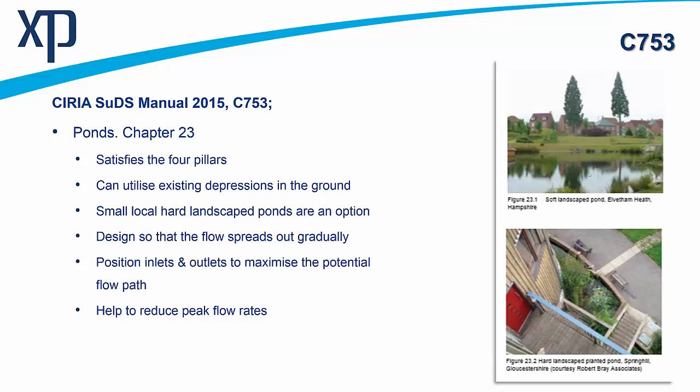We're not utilizing the full benefit of retaining that water for at least a 24-hour period to get the silts and the pollutants to drop out and give that final polish, that final clean to the runoff before it discharges off-site. We'd like to put in a long, tortuous path to make sure that that happens. There are some good examples of putting underwater bunds, actually, to create continuous paths below the surface that are quite neat to be aware of. And the ponds themselves will help to reduce the peak flow rates as well.